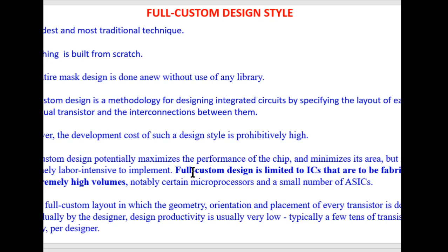Because of this, full custom design is limited to ICs that are to be fabricated in extremely high volumes. It is particularly suitable for those kinds of ICs which are to be fabricated in millions and millions of numbers. For example, microprocessors. The companies know that the microprocessor chips will be